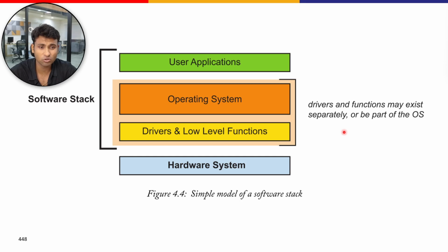Obviously, we cannot cover all the software stack possibilities, but we look at a more generalized and focused approach, which includes an adopted set which has Linux as the primary operating system implemented on the A53 processors and FreeRTOS deployed on the R5 cores in the RPU.